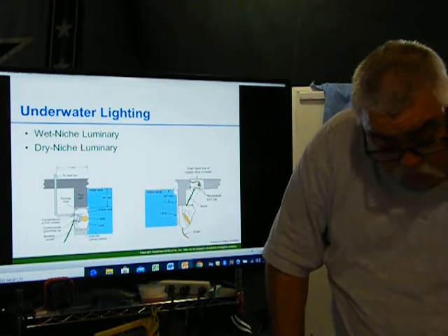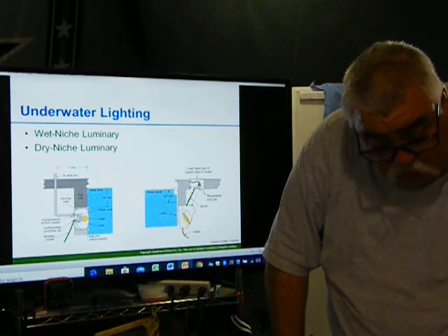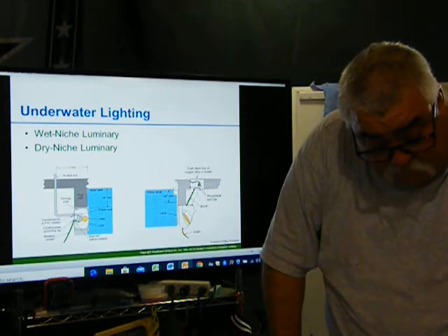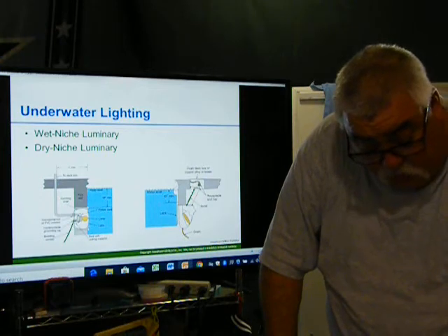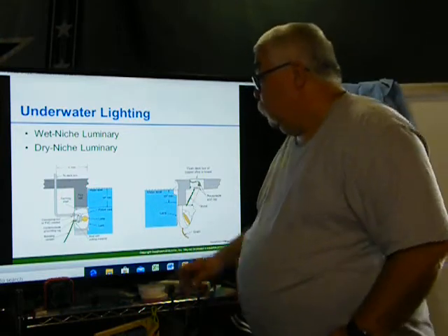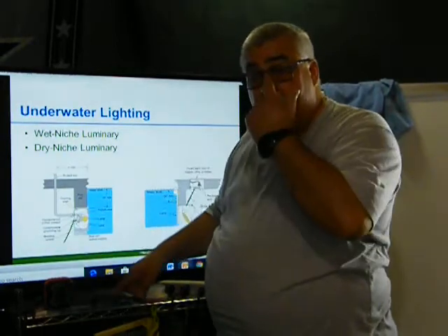It says when non-metallic conduit is used, a solid or stranded number 8 American wire gauge insulated conductor must be run with circuit conductors and attached to the inside of the grounding lug. Illustrated in the requirements for a wet niche luminaire. The code discusses wet niche luminaires in 680.23(B). Okay, so within this conduit, if you're using plastic, you've got to have a number 8 going there.